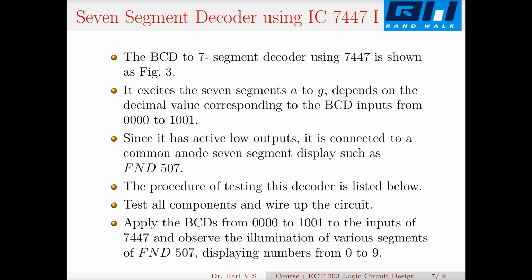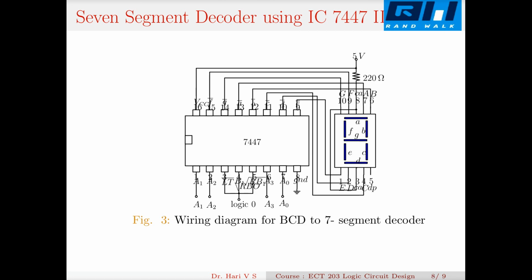So what it relies on is something called a 7-segment LED or 7-segment display. These LEDs are connected like a figure of 8 pattern. So if all the LEDs glow, then it is an 8. If F and C do not glow, then it's a 2. If B and C alone glow, it's a 1. That way you can represent the numbers from 0 to 9 with this.